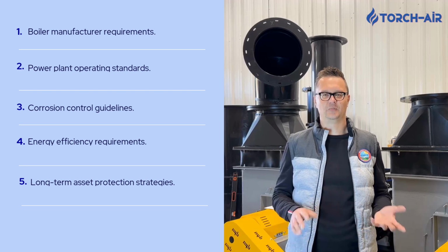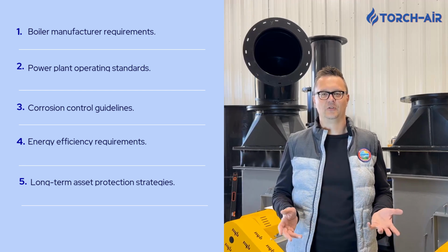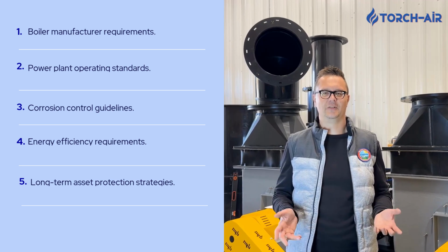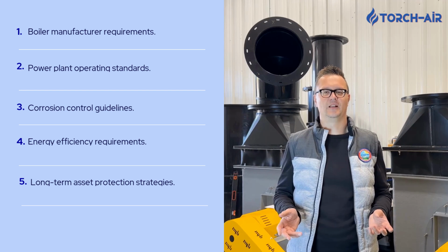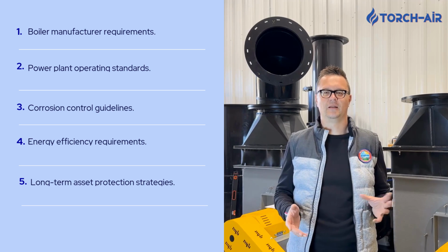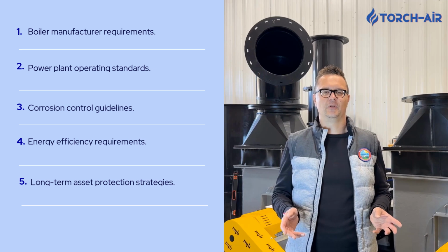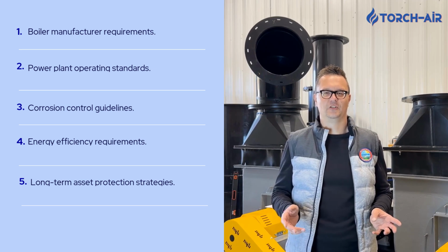Regulations and operational compliance. Oxygen control is driven by, first, boiler manufacturer requirements. Second, power plant operating standards. Third, corrosion control guidelines. Fourth, energy efficiency requirements. Fifth, long-term asset protection strategies. Deaeration is rarely optional. It is usually mandatory.